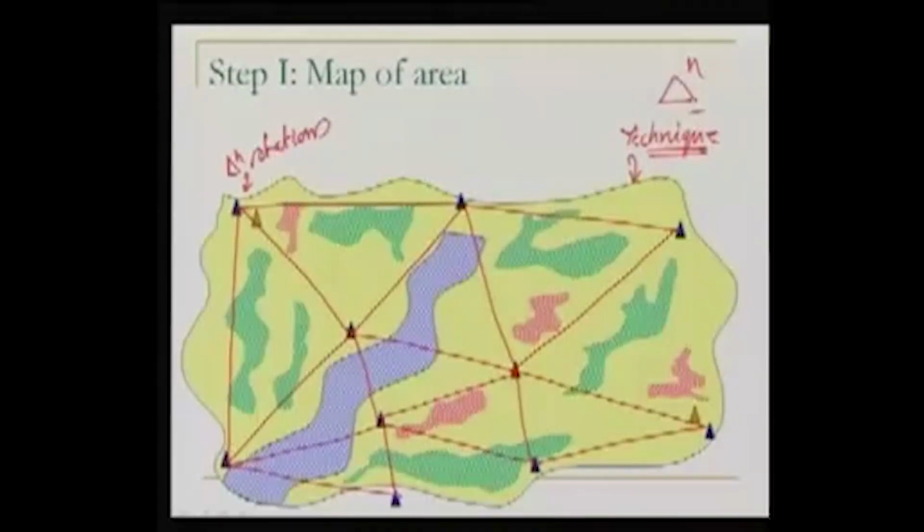One of the lines, for example this line, can be measured easily. So I'm drawing this line now, I'm rather highlighting this line. So that's our baseline, and then we measure the rest of the angles. All the angles are measured, so we know now the triangulation can be done, and we can compute the coordinates of all the points which form our triangulation network.